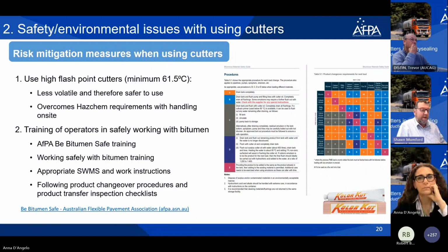And in the slide, you can see I've got another little picture in there, water finding paste. Any operators that are working out in the field, having a good understanding of whether there's any contamination with any products they're using is paramount, and any good contractor that's transporting or working with bitumen in the field should have that water finding paste with them.